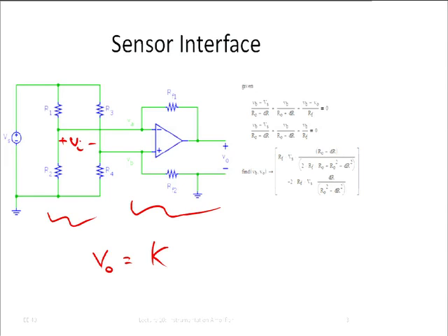But in reality, and I've shown you here the result, this is the output voltage, and that's the equation for it. If you look at the equation carefully, it's a reasonable approximation of this thing here, but not a very good one. What's the problem? The problem is that current flows into the amplifier, and that current upsets the value of VI. So how could we fix this situation? We want to put an amplifier there, but apparently we really don't want current to flow into our amplifier. How would we do that?